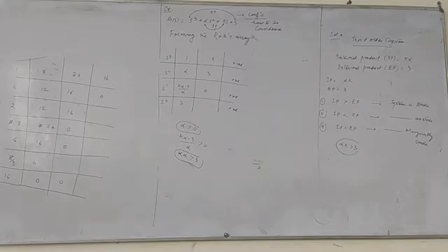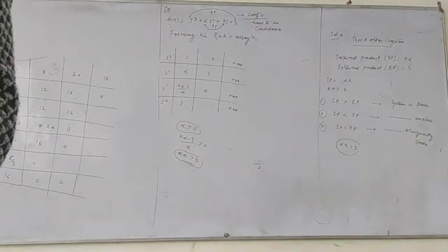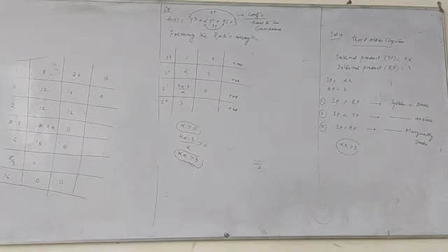So denominator very clearly is the characteristic equation. What you are going to do? You are going to take a denominator, find the Routh array, and then how we can say that number of poles on the RH side? Once you find the Routh array, then you will see the number of sign changes, exactly. Do it within 1 minute. You should be able to do this question. This is a very simple question. A layman can do it.